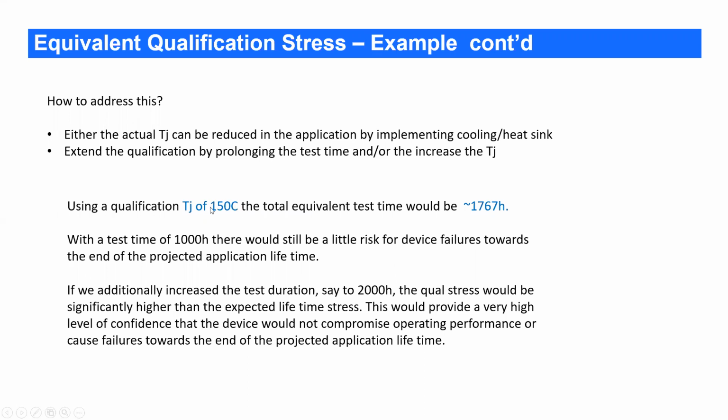The next step would be to increase the test time, because you cannot take the devices, the silicon, higher than 150, as this is the absolute max temperature that a piece of silicon can take without any risk to damage it just because of the temperature. And if you would do the same calculation with 150 C for 2,000 hours, you will be safe at the end. Your level of confidence is very high that the device can survive the target application stress over the entire lifetime, and not only survive, but maintain the defined and specified performance.